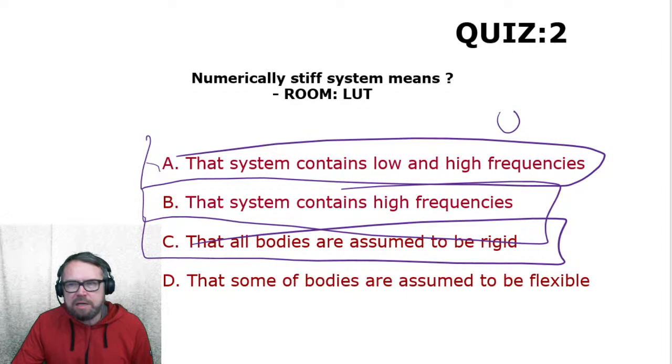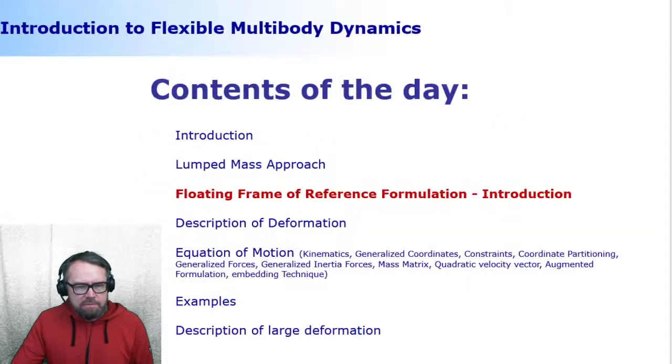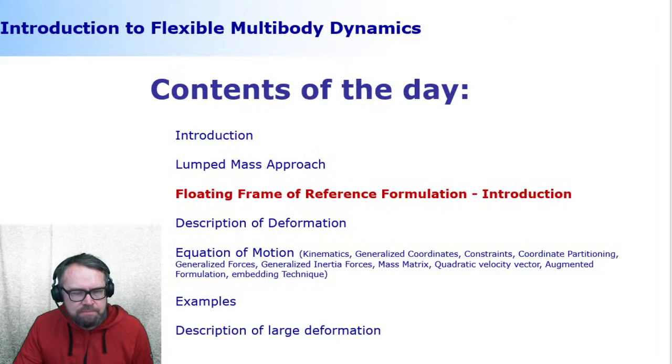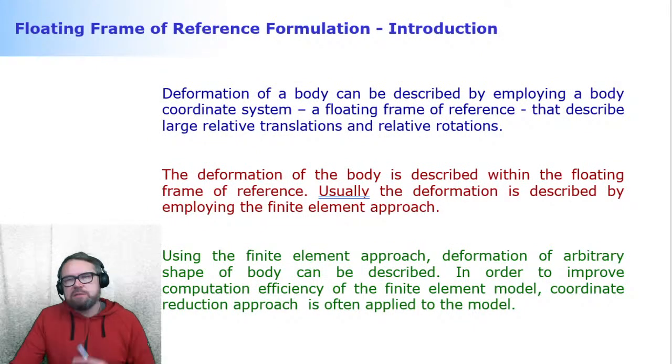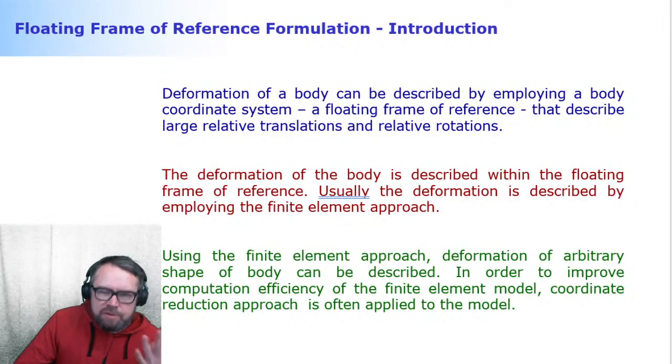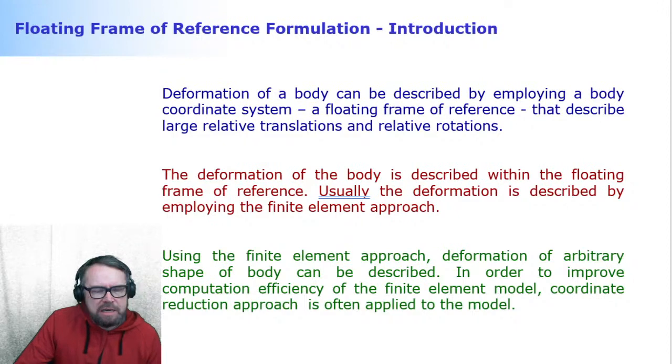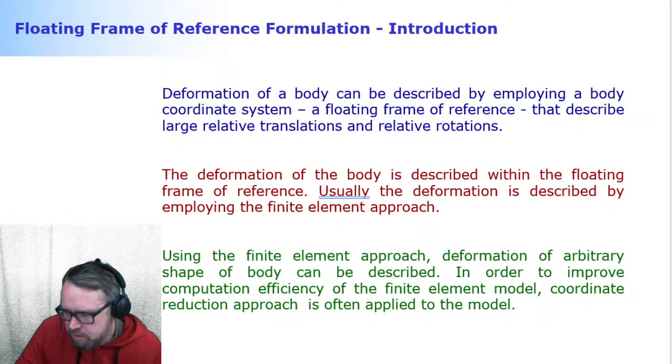Okay, with that, we're going to move on to floating frame reference formulation. Introduction first, and then we're going to move on to finite element modeling. 20 minutes, so I think we do have time to look at the finite element modeling. Now, floating frame reference formulation is conceptually very different from the lumped mass approach. This is the method that is heavily used, and I would say that there's no commercial software without the ability to model bodies using the floating frame reference formulation.